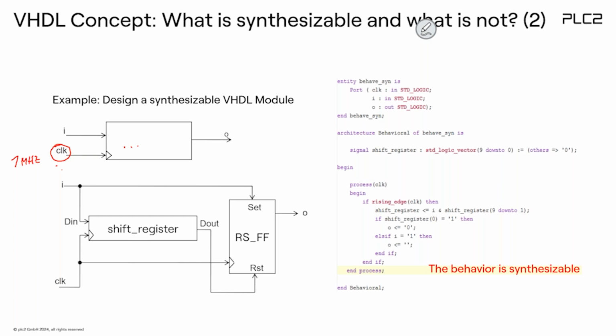Okay, so what would be the internal operation? Well, there are a lot of different solutions possible, but maybe the best solution is this. I would have the pulse which comes in, set the output immediately, and then it is a shift register. Because it's a pulse, the one is just stored here, and then the one is moved with the clock.